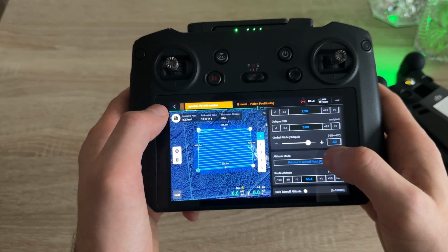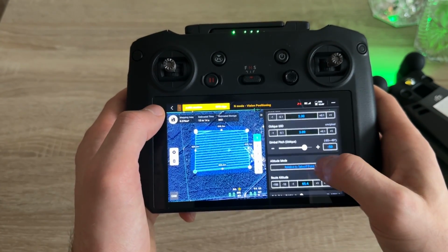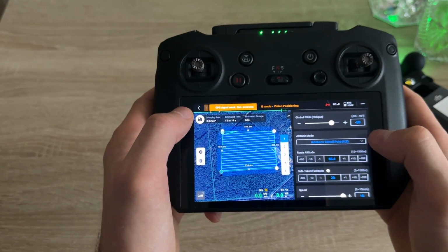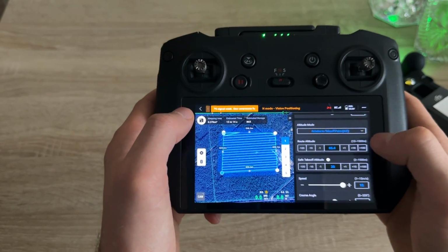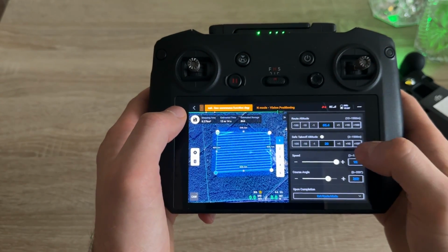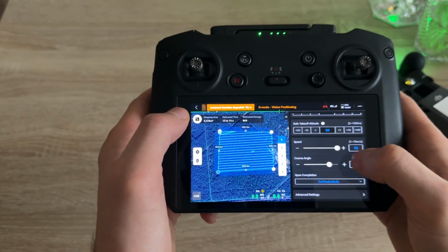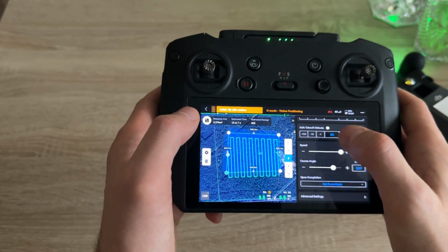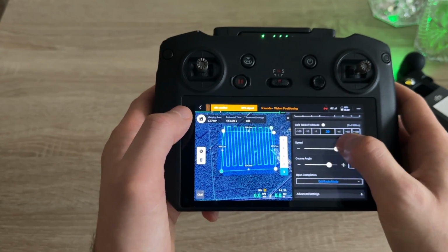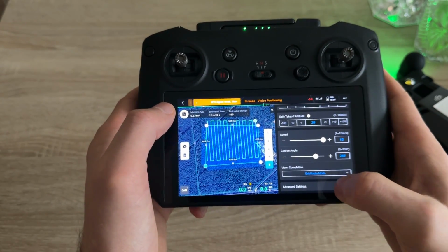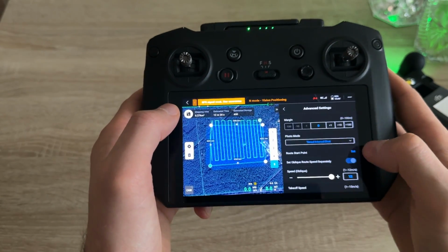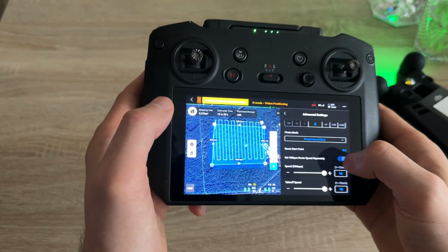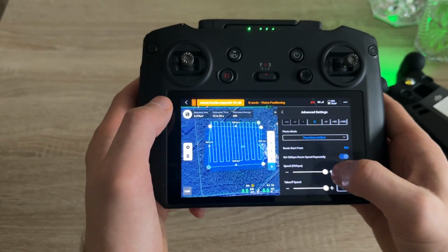If you want more angle, then you have to make more road missions. Also the same settings: road altitude, safe takeoff altitude. You can set the same speed or different speed for oblique missions. It offers an option to set oblique road speed separately.